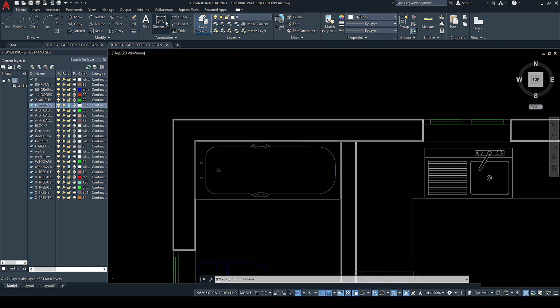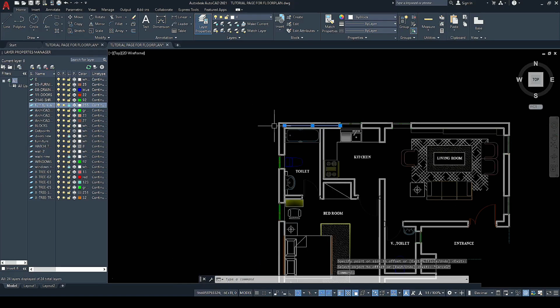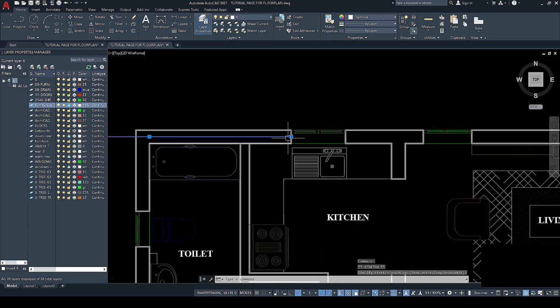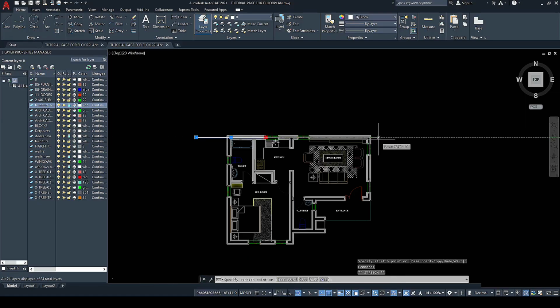what's the width of our wall? Our wall is 225 mm. So half of 225 is approximately 113. So you offset inward this way, so you can stretch the line out. You stretch the line out also in this direction.